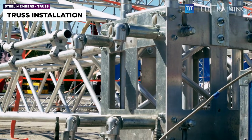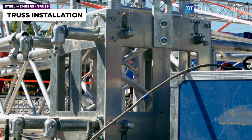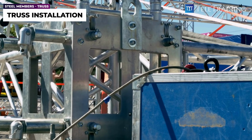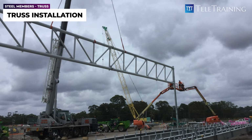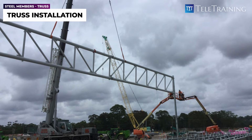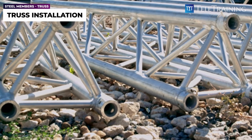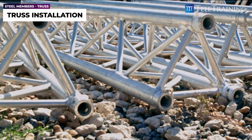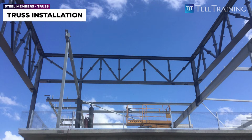As mentioned earlier, trusses are massive in size, so it's important to understand how they are installed on construction projects. In many cases, transport limitations and the nature of the installation process dictate aspects of the truss design. To address this, trusses are manufactured in segments and then installed piece by piece. For example, if you look at this truss, you will see that it has been manufactured in several segments. These segments are then joined together on the construction site to create the complete truss.